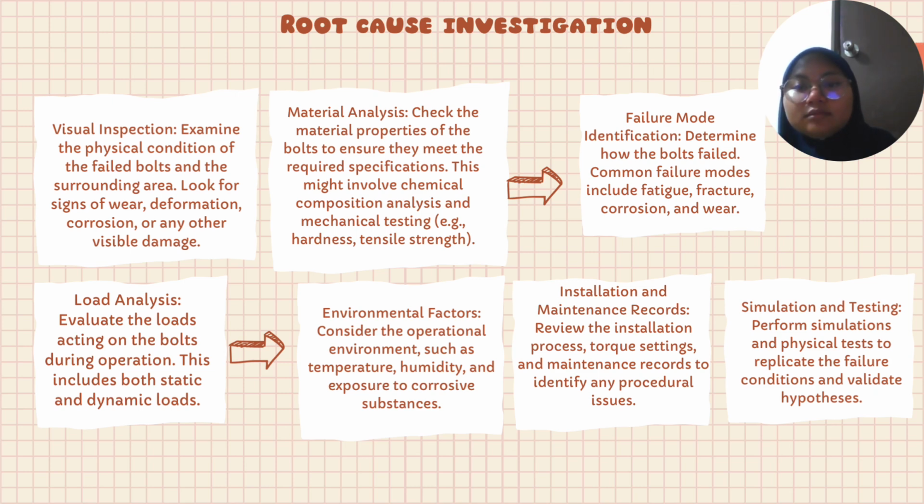For installation technique, environment corrosion, and unsuitable board design were the main reasons for failure. Stress concentration caused fatigue cracks to isolate from the board, and the improper size could not support the dynamic load. The board was further compromised during installation due to improper tool setting and insufficient clamping force.